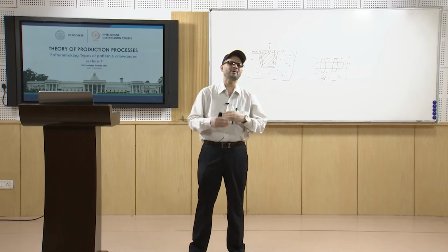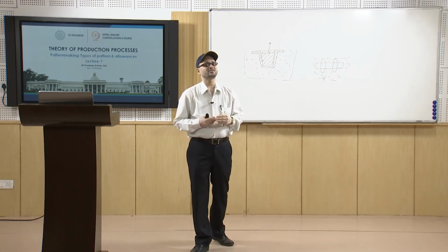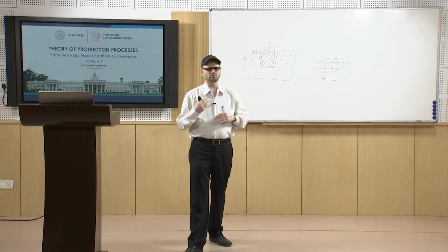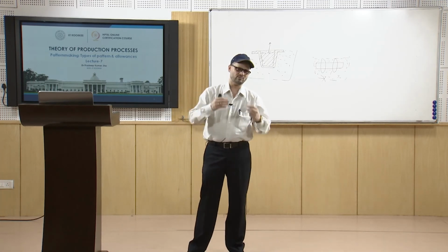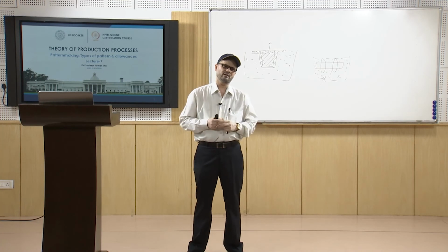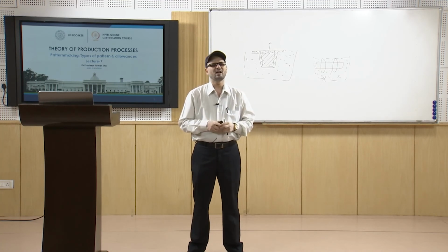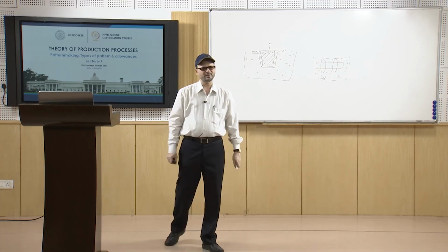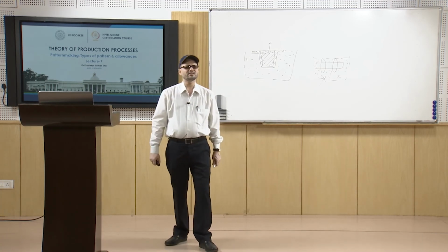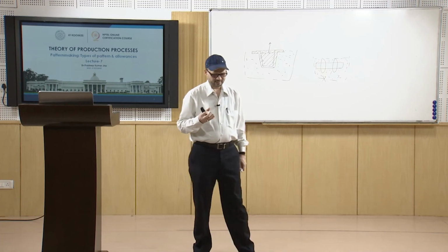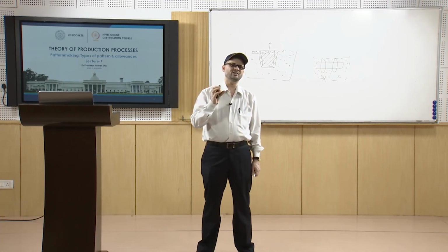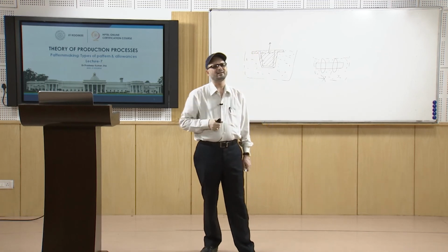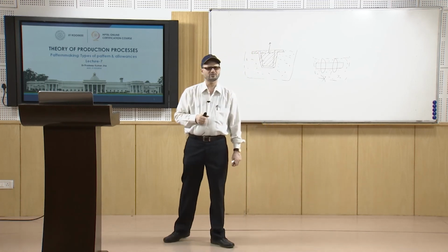So, when the criteria is stringent, you have to remove the top surface, polish it or machine it, and bring it to that particular level of surface finish. This is done for getting the proper finish of the material, and the allowance which you provide is known as machining allowance.